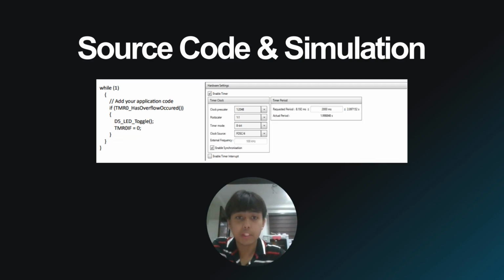This second code used in the main C file also used delay polling. It was observed that the LED switches between on and off at a time interval of 2000 milliseconds, or 2 seconds. The main difference is that the clock prescaler states the maximum time of the switching, which is 1 is to 2048. Aside from that, all the other codes are the same.